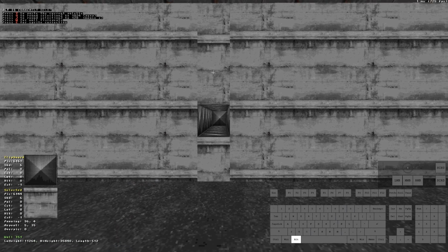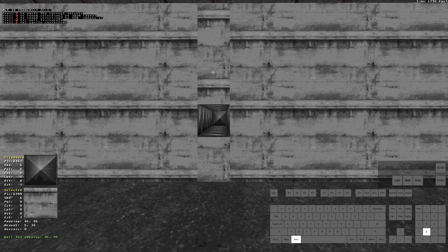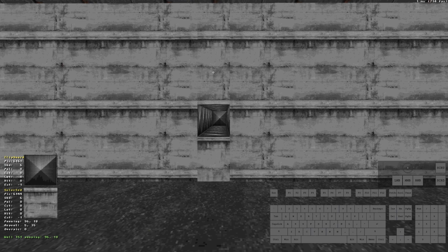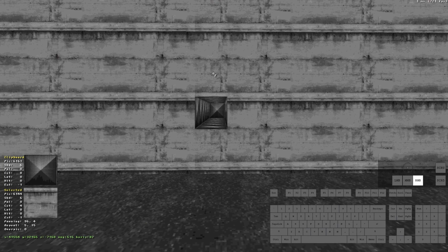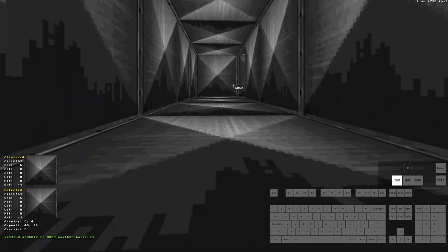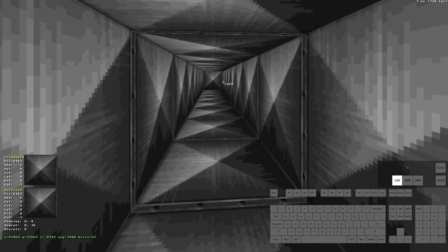When we created our vent, we divided this wall's textures and it became misaligned. We are going to fix it now. It seems there is no way to make it fit, right? We can go around this by pressing the O key. This changes the orientation of the texture to be either top or bottom oriented. Now the texture will fit when we try to fix it. If we respect the grid snapping, our vent texture will fit perfectly on floor, ceiling and walls.